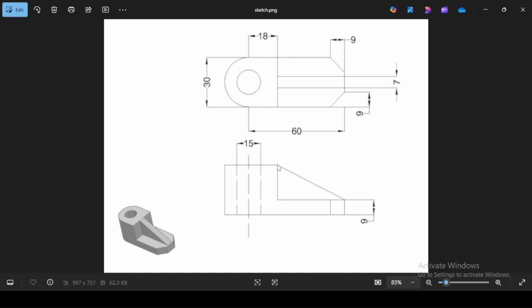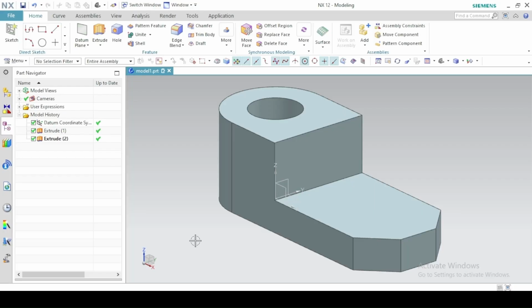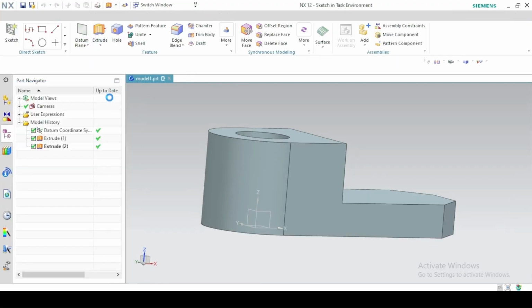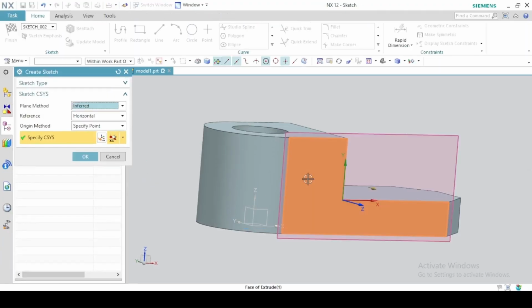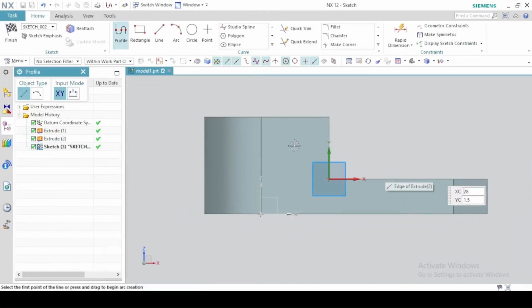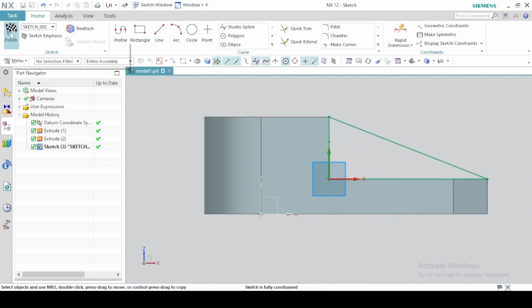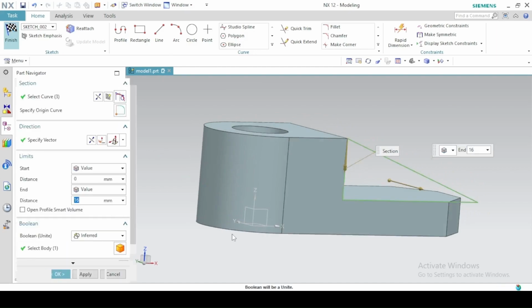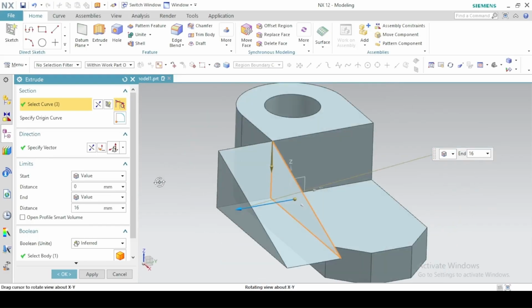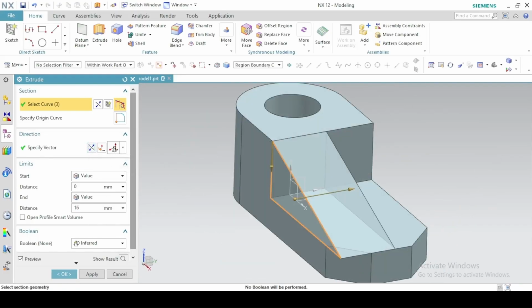And the last thing we'll do is to add this feature here to it. So you're going to draw from this face here. So click on extrude again, sketch section, and click this face here and click OK. Now we draw a triangle to touch these vertices. And then click on finish sketch. And we can rotate the drawing and then reverse the direction of the extrusion.